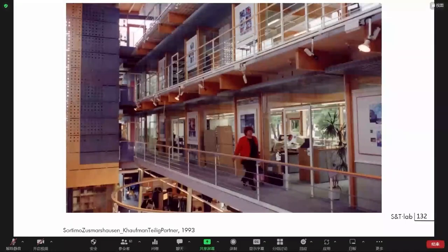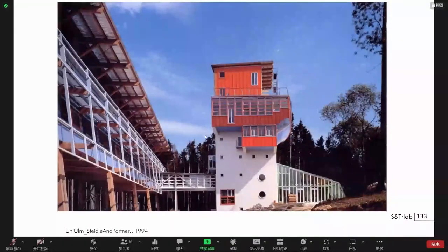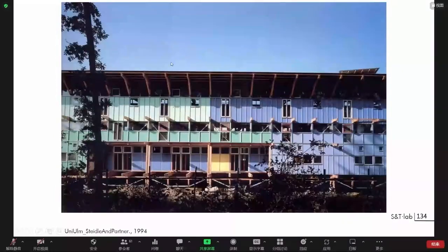You can protect it with panels that you can remove and replace, or you can protect it with a kind of cement or lime protection with timber. You see that the distance from the ground, distance from the roof, and an overhanging roof will protect the element that could in any case be replaced later. These are kinds of strategy you can have.